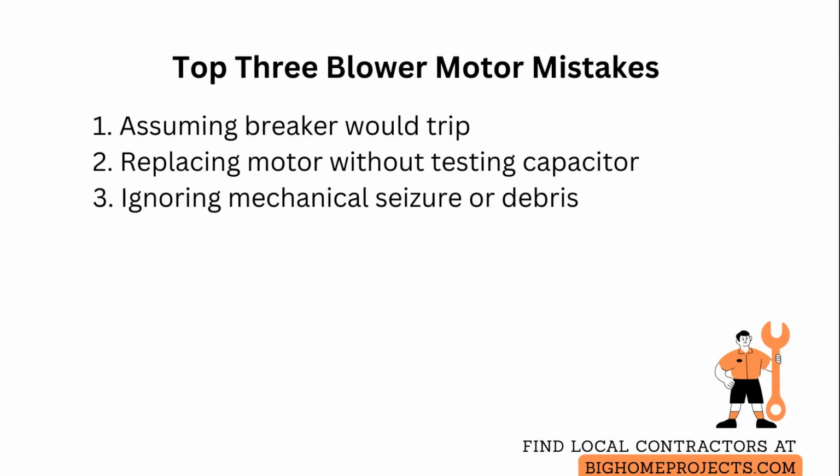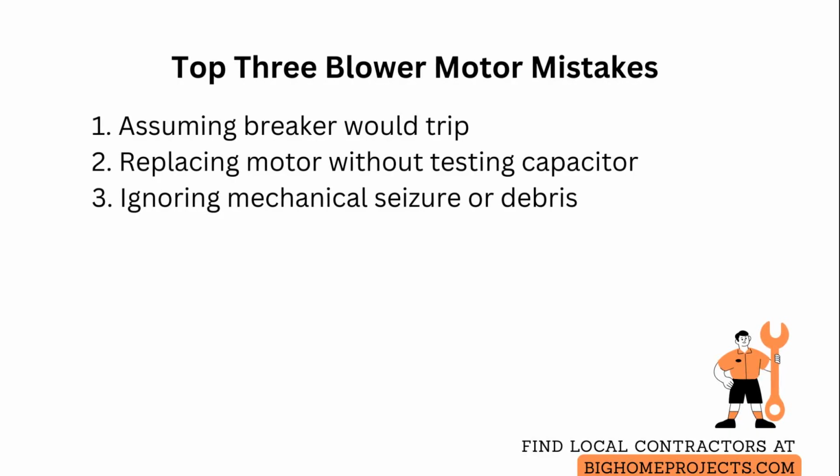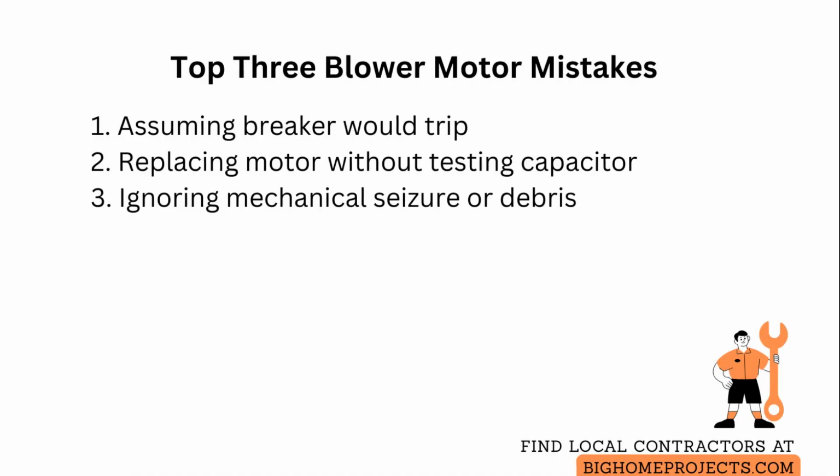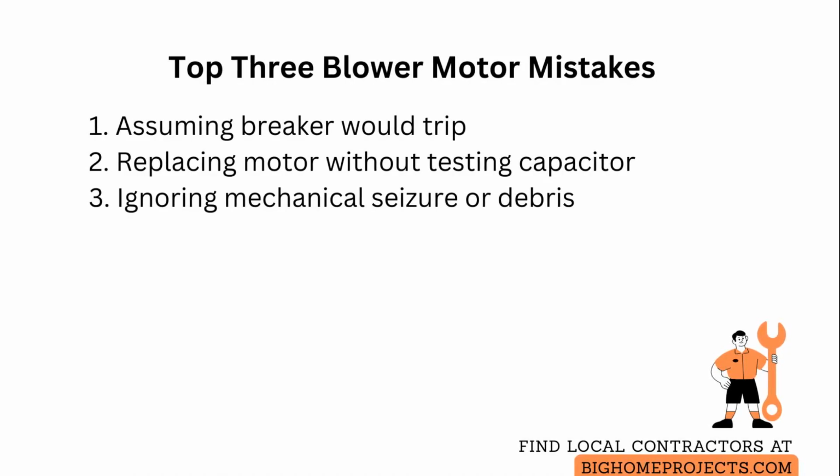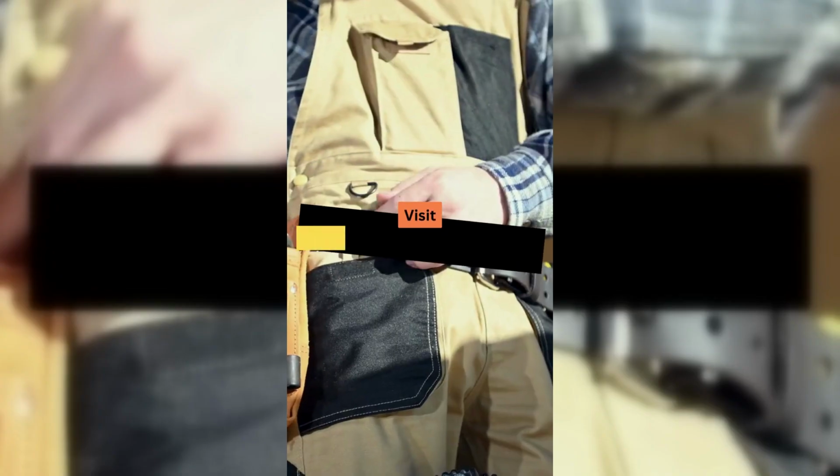People also neglect mechanical causes like seized bearings or debris, which can make the motor appear electrically dead. Perform a manual shaft check and inspect for obstructions before condemning the windings.